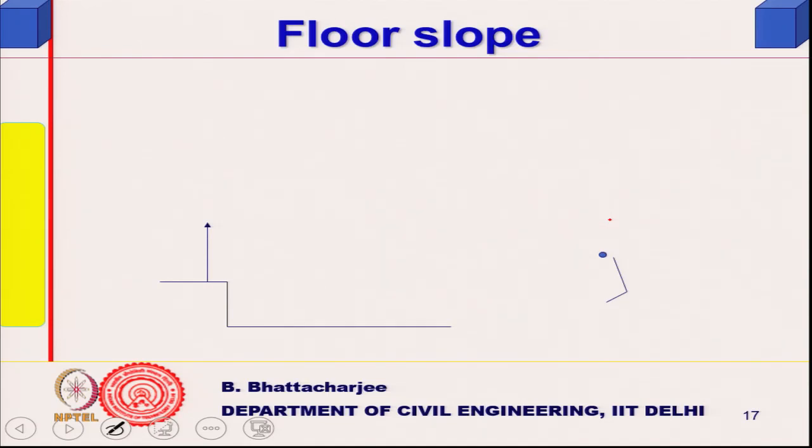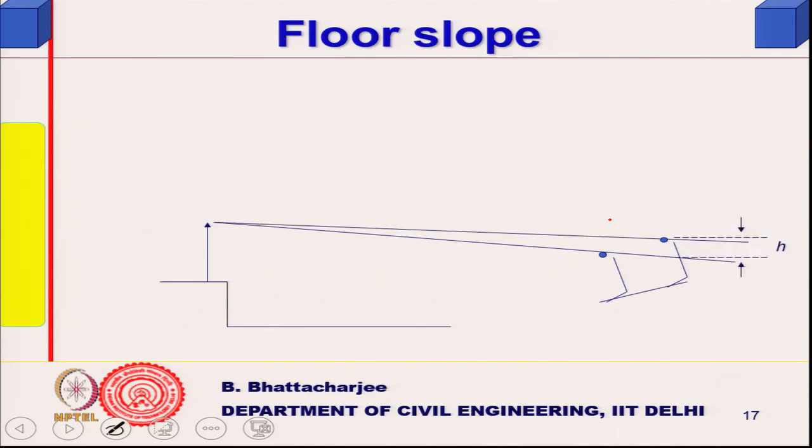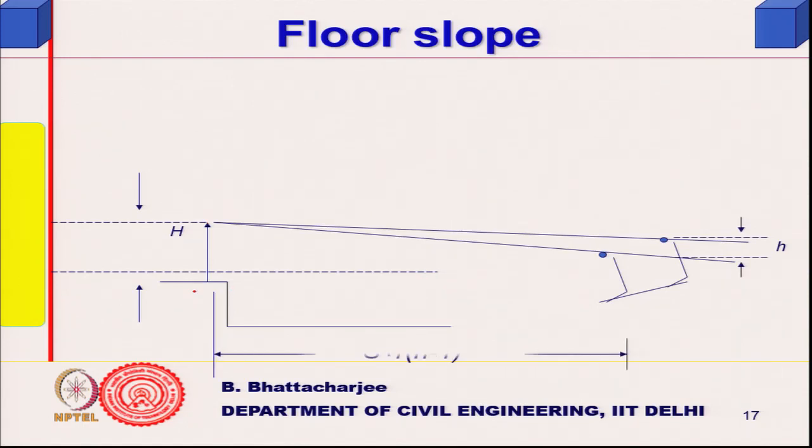Now, to find out a formula, there are 2 ways. One, consider a point up to S where you do not need any raise of the floor. Let us say consider 2 points where I need some raise of the floor. So, this is my ray from the source, and this should be the head clearance, and this line is the normal head level without any raise. Head level will be somewhat higher, we are talking of head level because hearing is at this level. So, head level, eye level, etc., generally we talk of head level. This is the elevation of the seat, E is the elevation of the seat, h is the head clearance, height of the source is H from the proscenium. If I draw a parallel horizontal line at the head level, this is E. So, if I extend this, spacing is R.